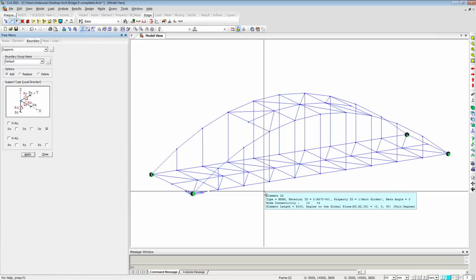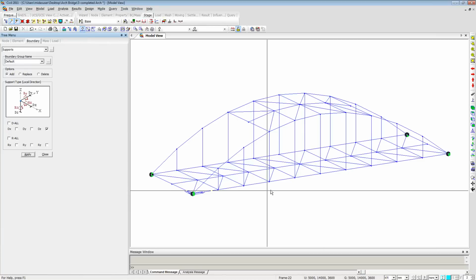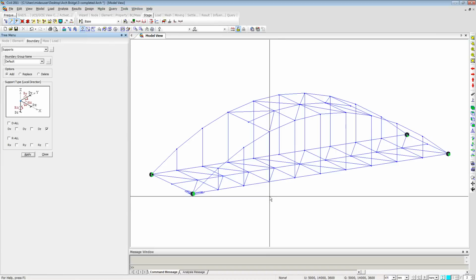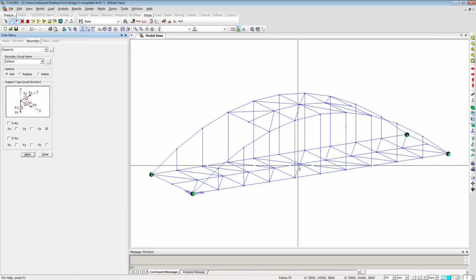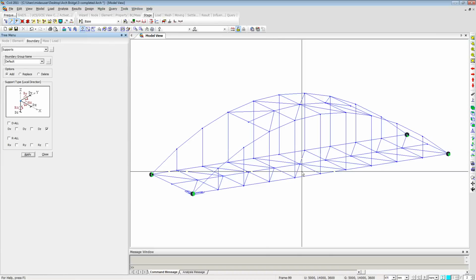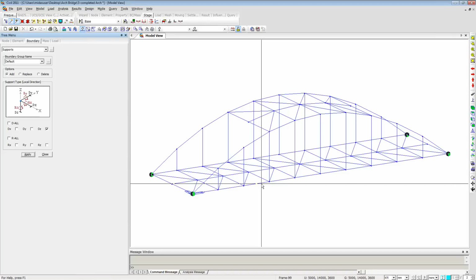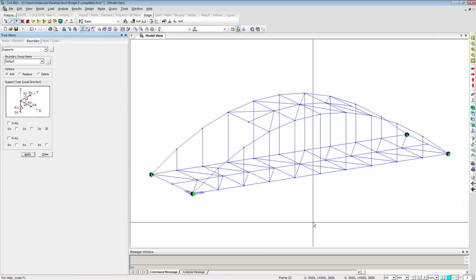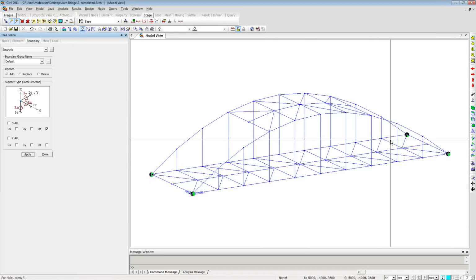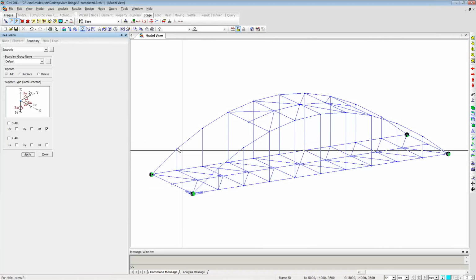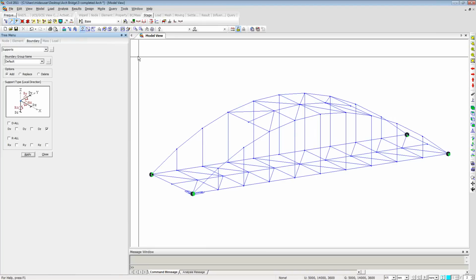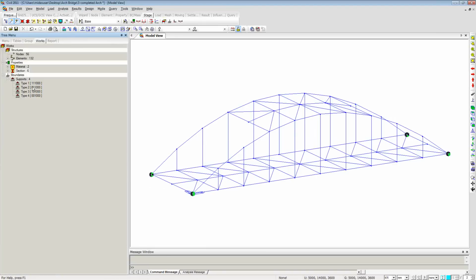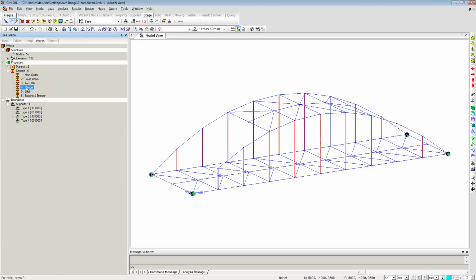So one more thing we have to do is to apply the end release on some of the elements, on hangers, braces, and crossbeams. So what I'm going to do now is select the hangers and end release them. So we could go to, let me close this, go into sections, hangers, double click on them, and they are selected.